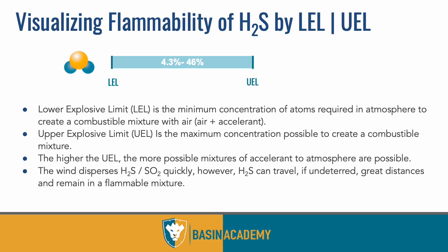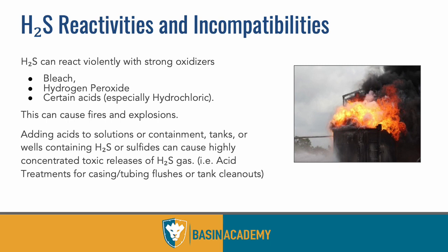So it's important to note that the distance that we are from this stuff can make us safe or not make us safe, depending on where we're at. So we want to make sure we're upwind, crosswind, because those concentrations can change. You may be at 8 parts per million one second and 200 parts per million the next, just in a snap of a finger. It is reactive with bleach, hydrogen peroxide, and certain acids, specifically hydrochloric acid.